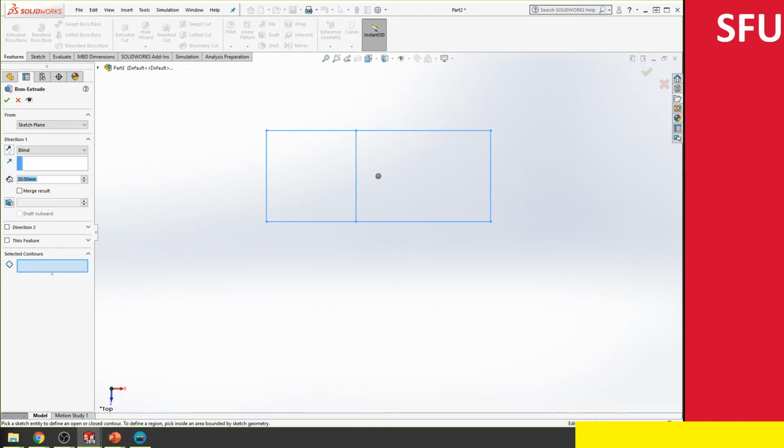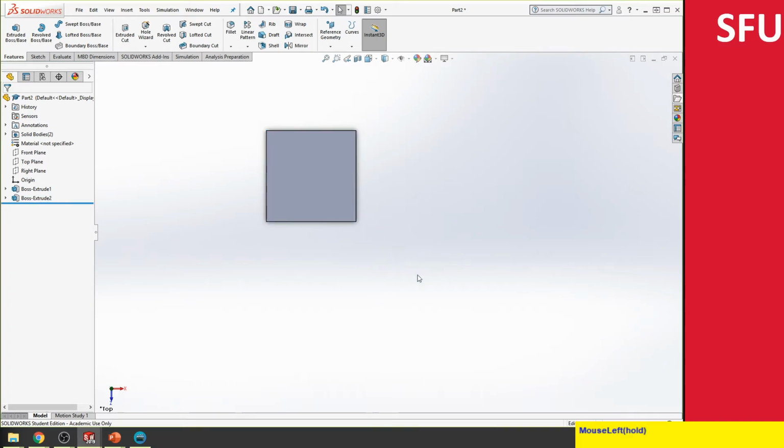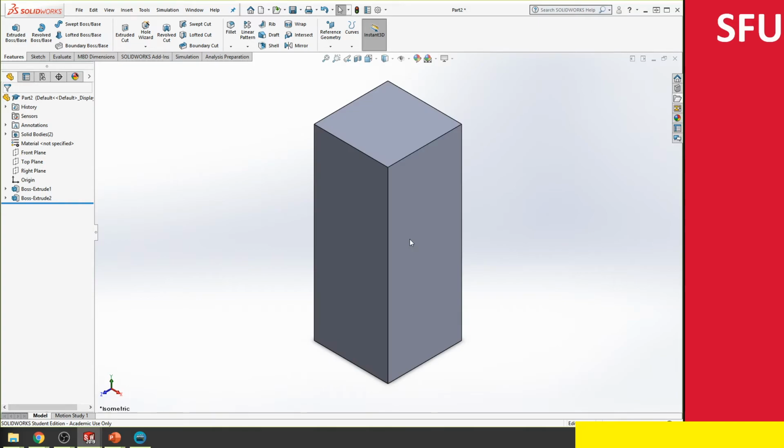Notice that unlike the previous attempt, SolidWorks did not give me a rendering of the image. The reason being, because there are two different contours, it was unable to figure out which one I actually want to extrude. So let me select this closed contour over here, and the height I might want to be about 50, and then say OK. You can just go into the 3D view, or I can hit Control 7, and that will give me this view over here.